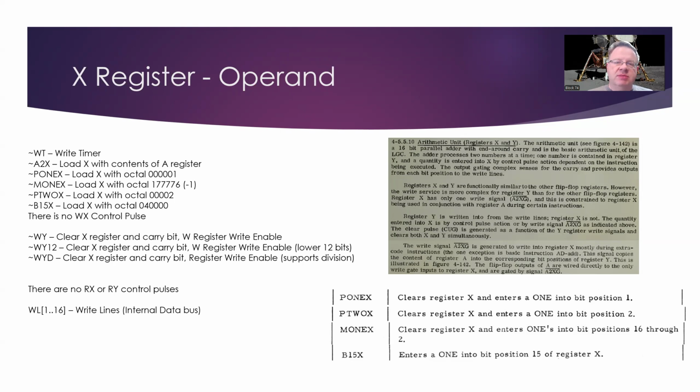They're similar to the A register that we talked about a few episodes ago. It does some of that OR logic with the write lines and some of the control pulses and the sequence of control pulses. And then it is also used to write data into the G register in certain scenarios, as part of storing data back into and out of memory. But back to the X register.